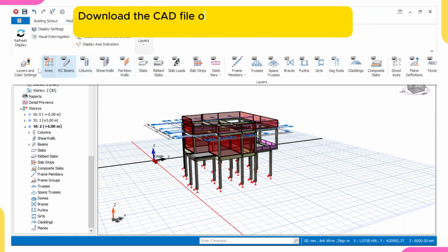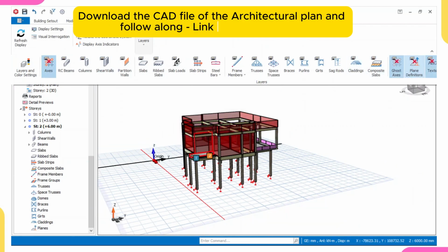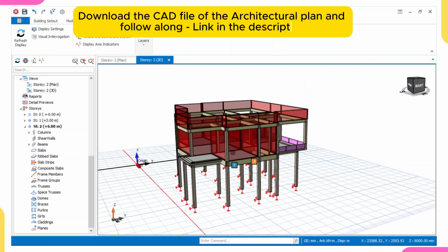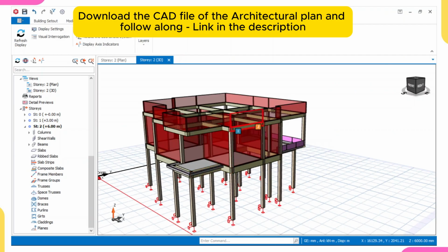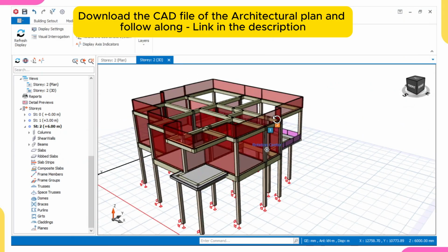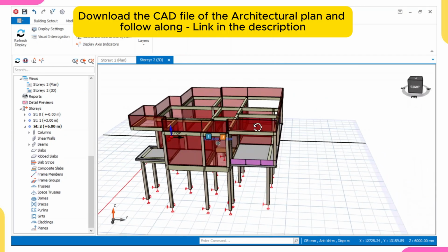But normally, if I'm doing a personal design, I will not apply this parapet load because I know even after I finish applying it, my design will still be passing. I'll still be having 2y16 in the beams. So that's why I don't normally bother applying it. But I just apply this because this is a tutorial, so people will follow on. Yes, so this is what we're having now. See how clear our model is.